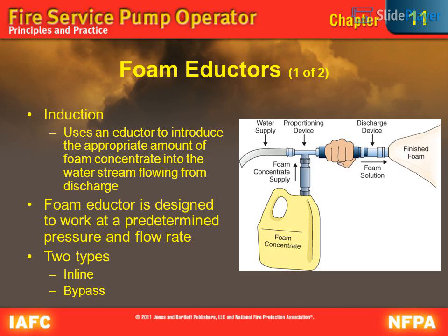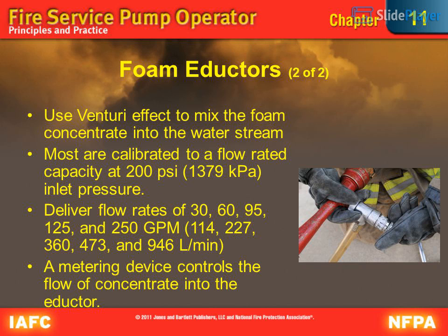Foam eductors, 1 of 2, induction. Uses an eductor to introduce the appropriate amount of foam concentrate into the water stream flowing from discharge. Foam eductor is designed to work at a predetermined pressure and flow rate. 2 types. Inline. Bypass. Foam eductors, 2 of 2.